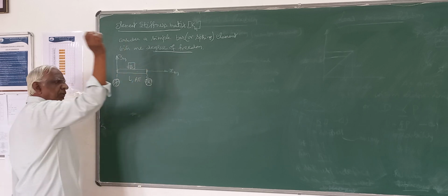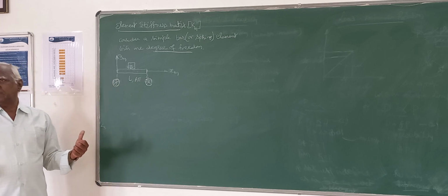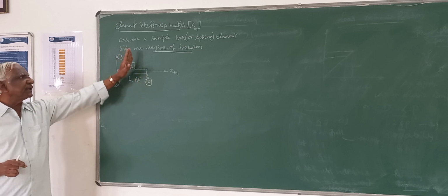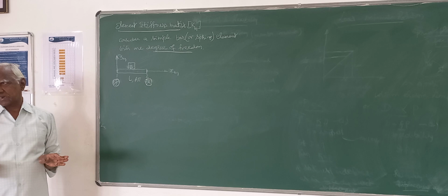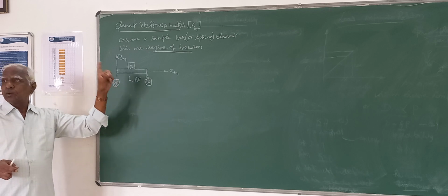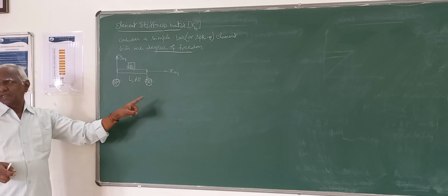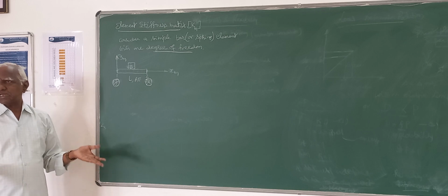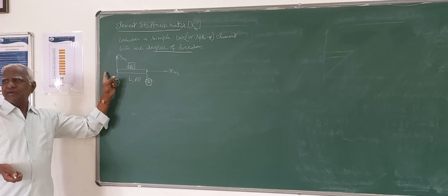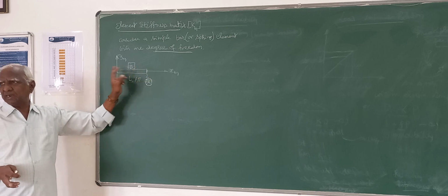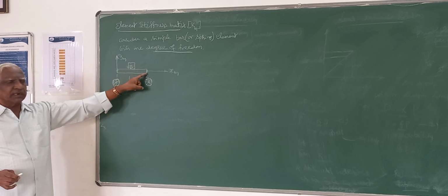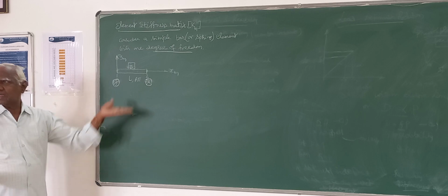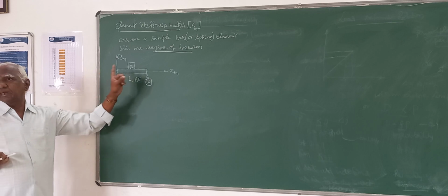Though the element has an infinite number of points, we don't deal with all of them. We deal only with the end points, which we call the nodes, and knowing the properties at the ends, we can interpolate the value at all other intermediate points. So during our analysis, we determine the unknowns only at the end points, Jn and Kn. Strictly speaking, we first determine them at the ends, then we can plot the bending moment diagram or shear force diagram, which represent the internal stresses at all other points.